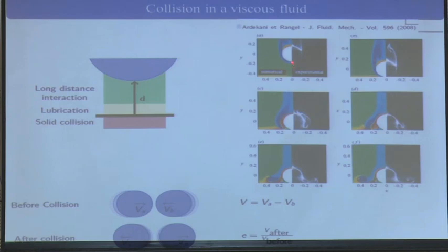When the particle is coming close to the wall, this fluid has to escape. So you have to drain that liquid, and draining the liquid needs energy, and the energy which is available is given by the particle. So during the motion of the particle towards the wall, it will lose some of its kinetic energy because of the drainage of the liquid film.